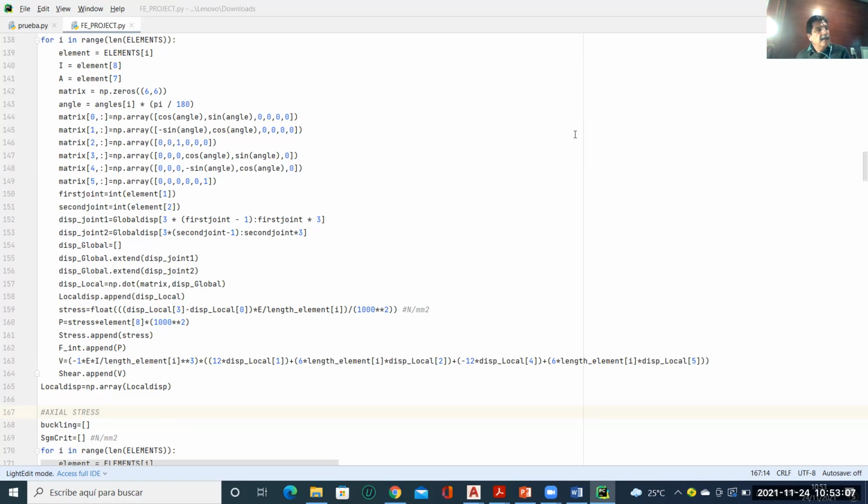Okay, people. Nice work. The problem with your report is that I don't see any convergence study. I just see one single model, right? How can you be certain that your results are adequate?